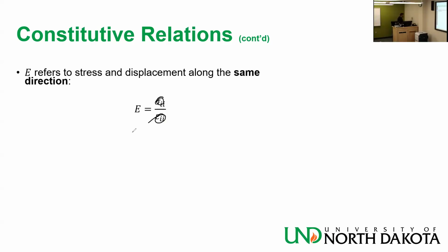And it's very easy to measure the Young's modulus of a material in the lab. You put the material, measure its height, put a weight on top of it, measure its new height. It should be shorter than before. So it's the opposite of the problem that we saw in the previous slide. It's not an extension, it's a compression, a compressive stress that you apply.